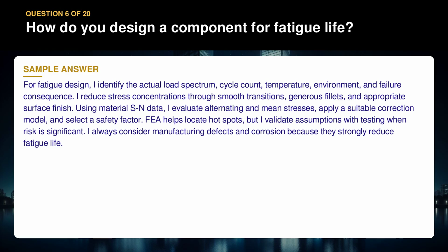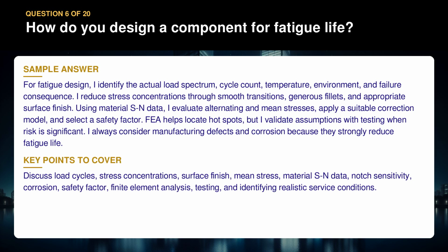FMEA helps locate hot spots, but I validate assumptions with testing when risk is significant. I always consider manufacturing defects and corrosion because they strongly reduce fatigue life. Discuss load cycles, stress concentrations, surface finish, mean stress, material SN data, notch sensitivity, corrosion, safety factor, finite element analysis, testing, and identifying realistic service conditions.